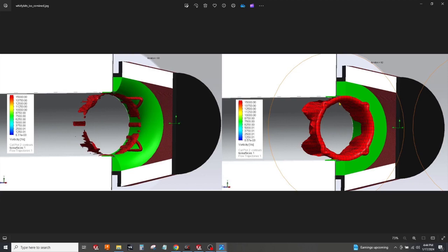And that's really what's going to be driving the reduction in flow rate when you don't have that velocity stack in there. And so the end goal here is to actually minimize this as far as possible. Obviously, I haven't done that here in this design, but we're certainly getting close. We've made a big improvement. And the takeaway from the earlier results that we talked about in the table was how this is very proportional to velocity.